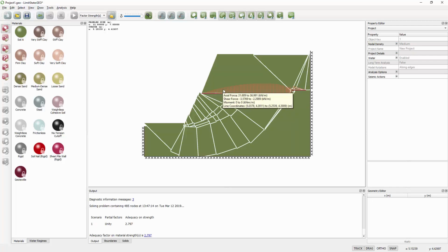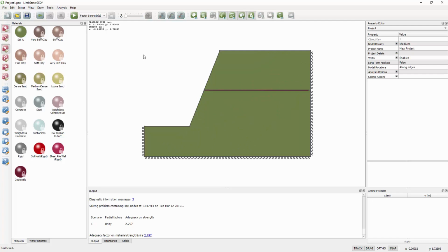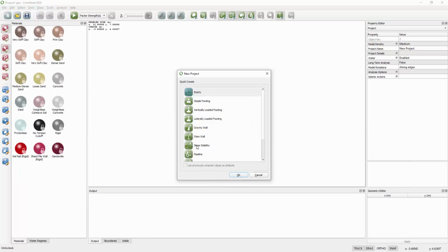And the software also plots out, in this case, the tensile force in that geotextile along its length as those stresses are transmitted from the soil into the geotextile. So the answer is yes, it can. I can't really show the full capability in this very short period, but that's one illustration. And you can also use this one-dimensional element to model, for example, a sheet pile wall. And there is actually a wizard that allows you to model that.